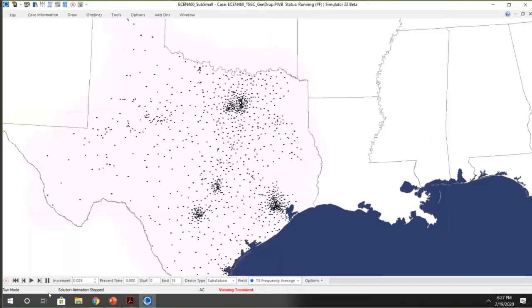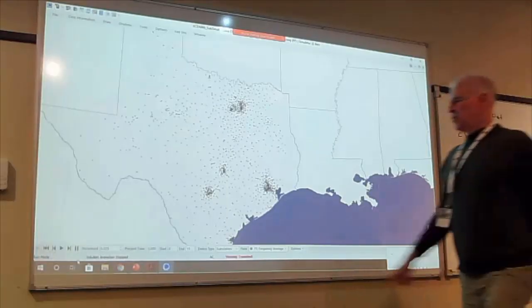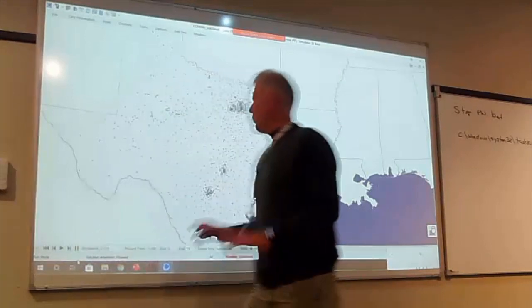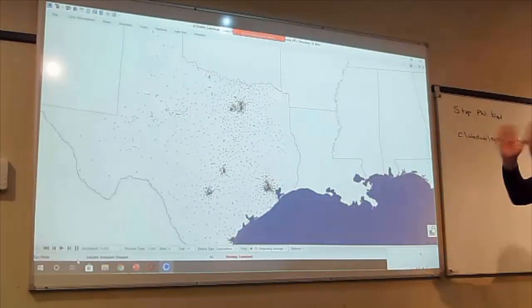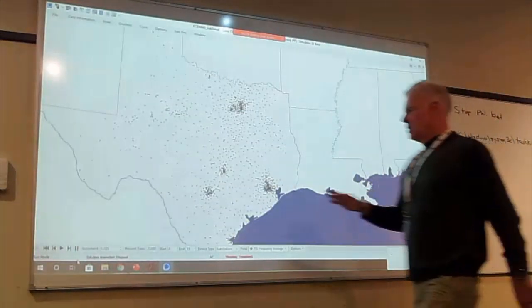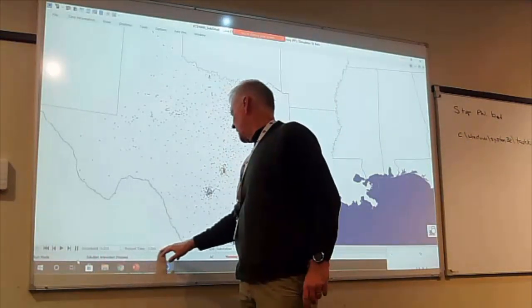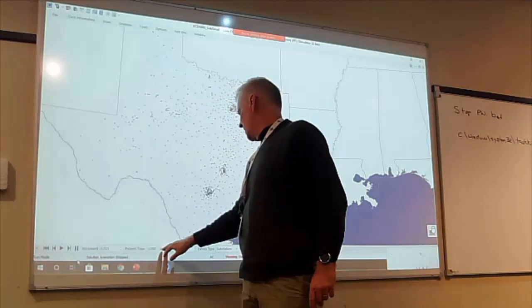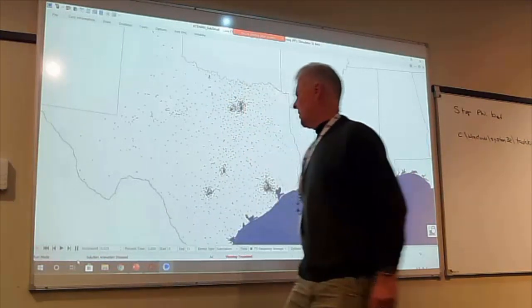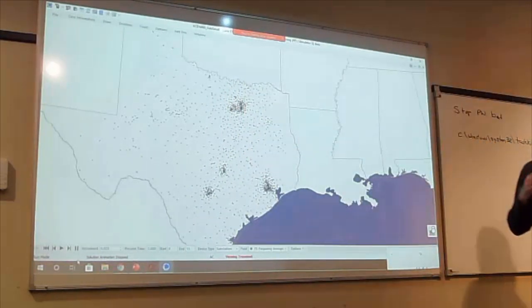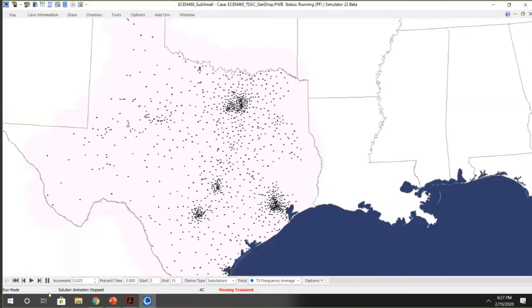So once you've got this, just click the play button here, and what it's going to do is go through sequentially your transient stability results, picking whatever increment you decide from the start time to the end time, and create a contour. And we'll see it kind of playing in real time here. These are all JPEGs that can be saved and strung together in a movie. So just click that.